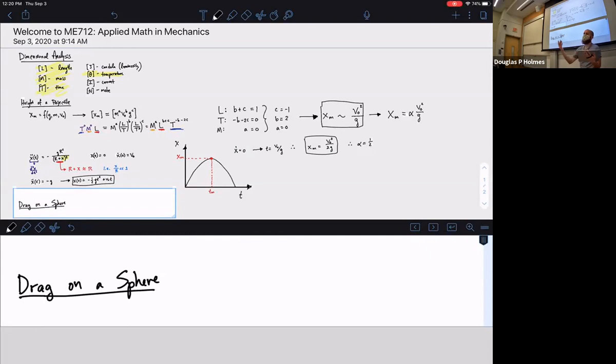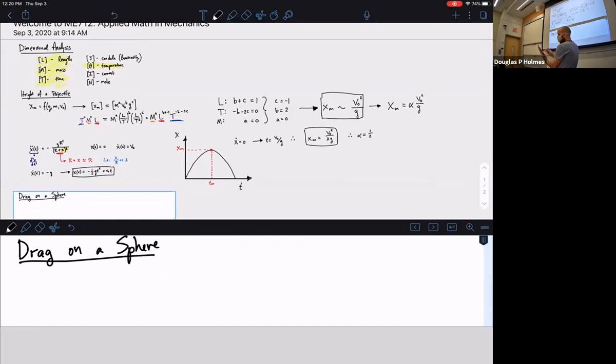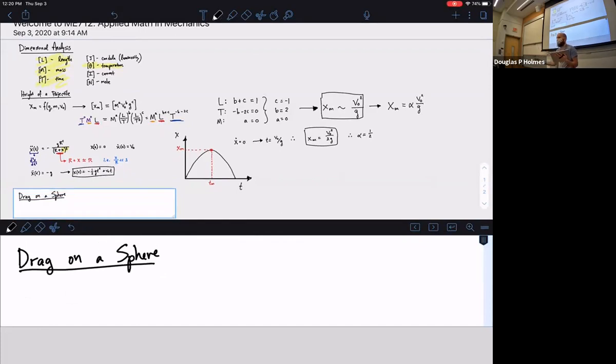If you don't do anything in fluid mechanics, you might be unfamiliar with why we would care about drag. Drag is the force that's essentially slowing something down as it's moving through a fluid, whether that fluid is air or liquid. It's a crucial design parameter for designing automobiles, racing bikes, ships, and the idea usually is you want the drag to be as low as possible. So we want to know how the drag depends on the various parameters of our problem.